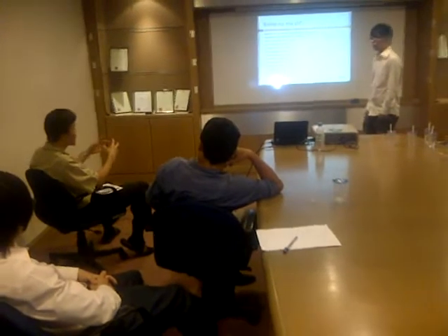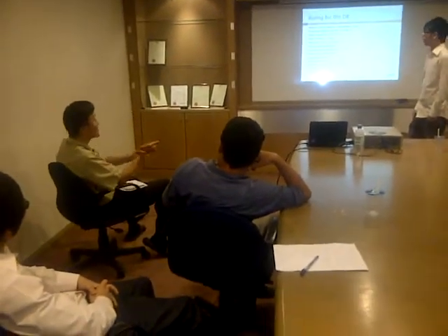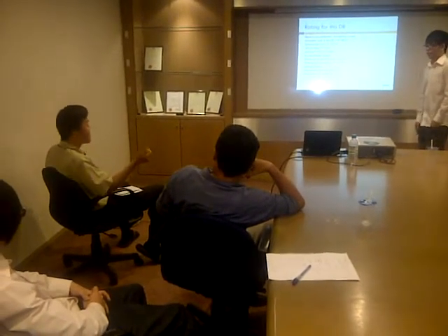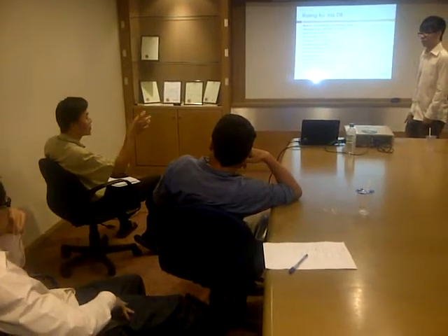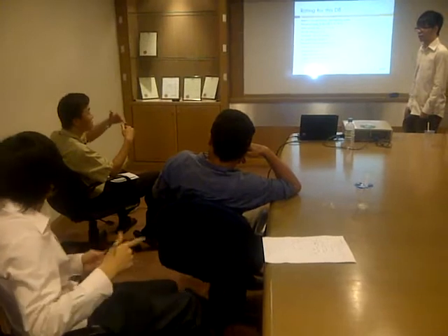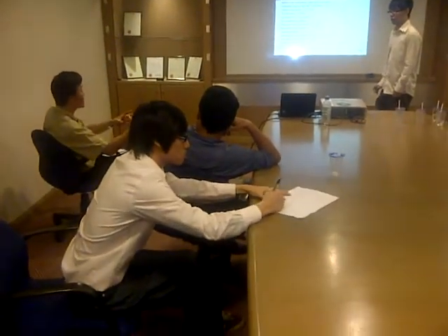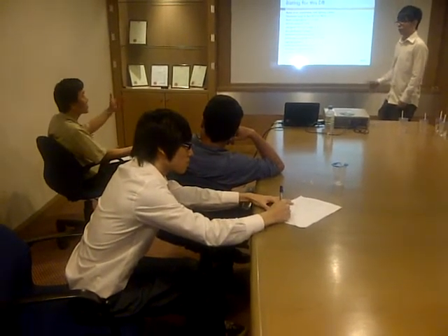So you must size the cable according to the current rating of the breaker, not based on your maximum demand. Definitely not. But you size your breaker based on your maximum demand with some additional spare load. Means you know your maximum demand is 100 amp, but I may need to cater for a little bit of spare load, normally 25%.